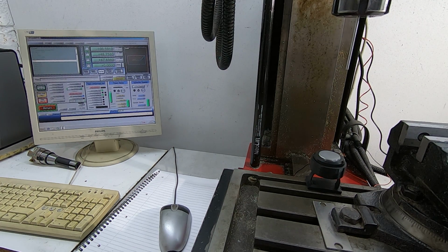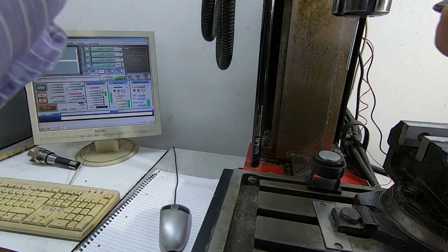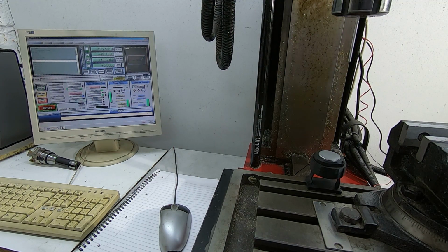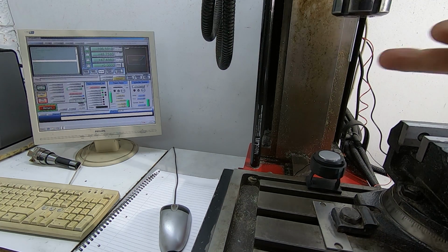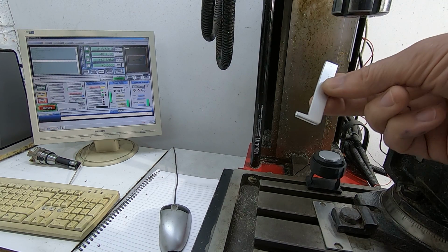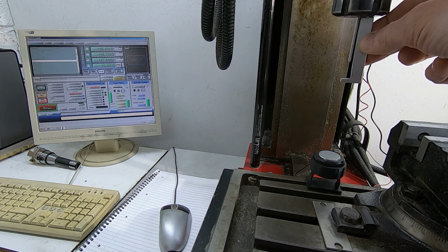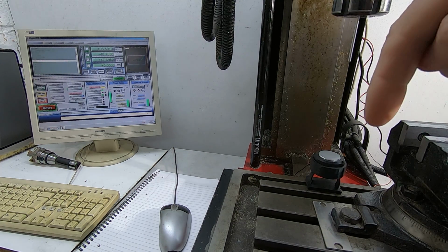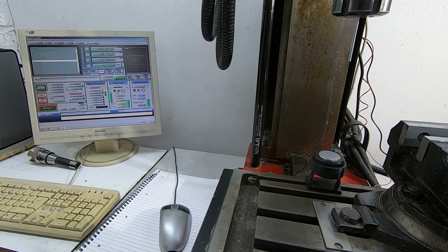So I'm going to shorten the tool. Okay, so I've shortened the tool. By the way, the buzzing noise, there's a clamp on the end of the milling table which is making a lot of noise, so just ignore the noise while it's transitioning. I've shortened the tool. We'll check to make sure that it is shorter than our template, which is, as you can see, about 5mm shorter than it was. And normally if we try to continue milling without re-zeroing, it would continue milling, but it would do it well above the material we're trying to mill.